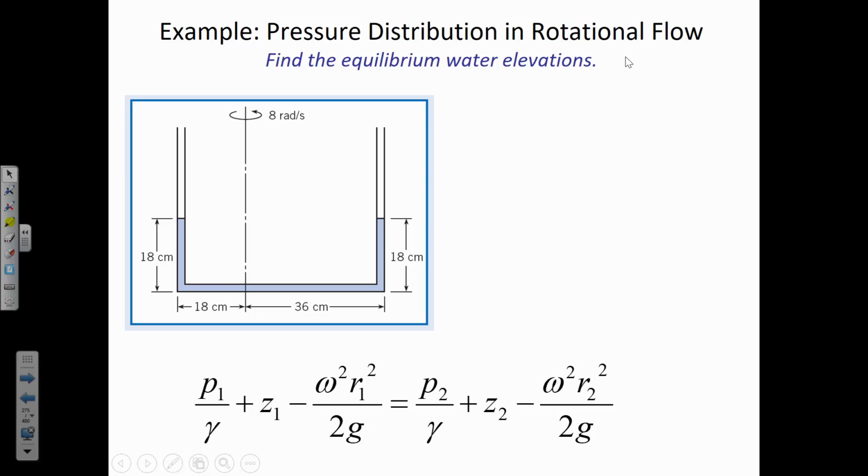Should we eliminate one of the arms and have it where one of them would be pressure of 0, radius of 0? Okay, that's a great question. He's saying, well, what if we just had one of the radiuses be 0? So we can't move where it's rotating about. Like, the system is rotating at this location. And besides, we know R1 and R2, so the R values aren't the information that we're lacking. It's the elevation that we've got too many unknowns on.